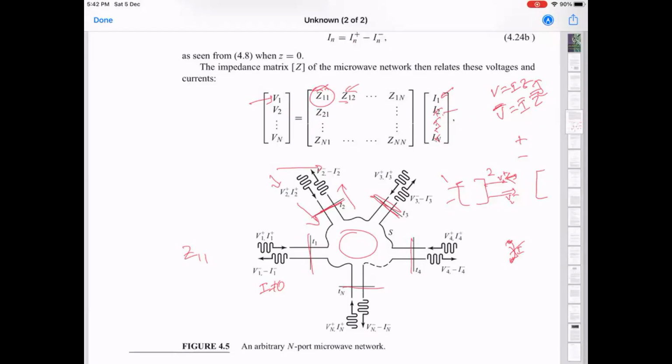Again, if you actually knew what the network was, in the sense that you have a circuit representing that network, then you can use the same idea to compute the actual quantity. And that's what we will do. We will go through one of the examples given here, and then understand the properties of such two-port networks in terms of this impedance matrix, and why the value is the way you actually calculate or measure it. Okay. So that's the definition of the impedance matrix and the corresponding admittance matrix.